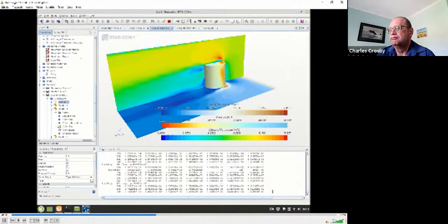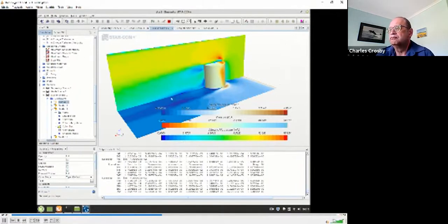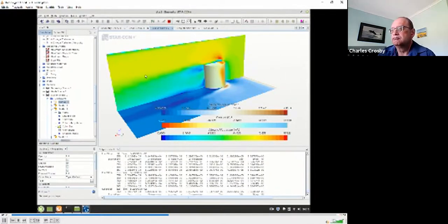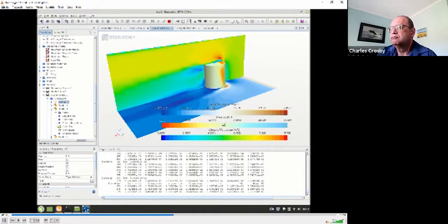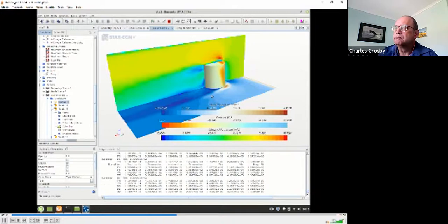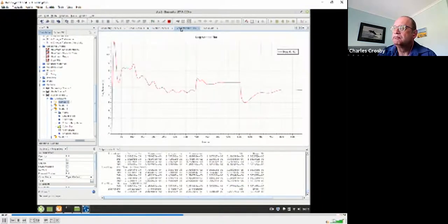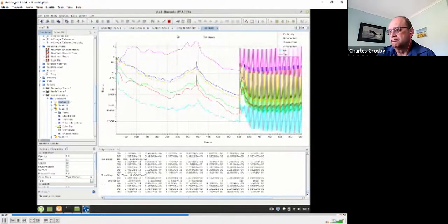We're now plotting 3 different variables. We're plotting a skin friction coefficient on the floor, plotting the magnitude of the velocity vector on the symmetry plane, and on the cylinder we're plotting the pressure, but we're using different pressure maps so that they don't get confused with each other. And see how the drag force is developing. You can see how residuals are developing.